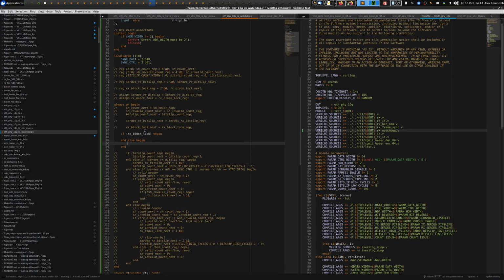And I think the way to do this is to have kind of a first pass that looks at numbers of various events that have occurred over a certain time period, and then the second one make sure that we see continuous problems over an extended time before we reset the transceiver, because we don't want to reset the transceiver when we see a couple of bit errors. We get bit errors. There's not much we can do about that. We only want to reset the transceiver when something is actually totally wedged and totally screwed up.